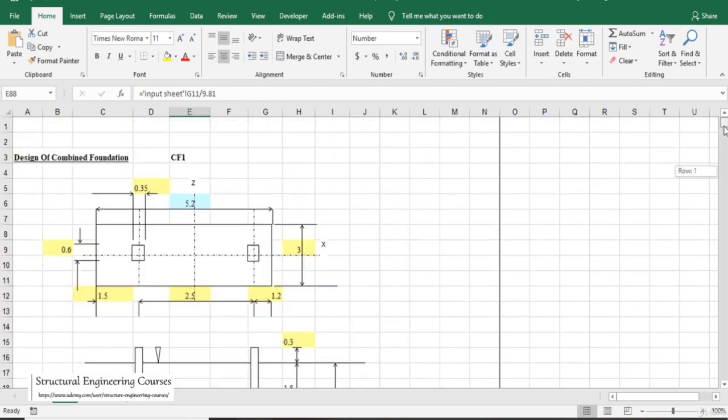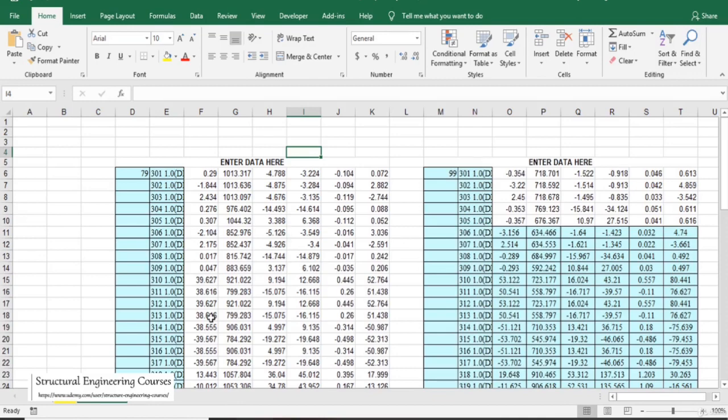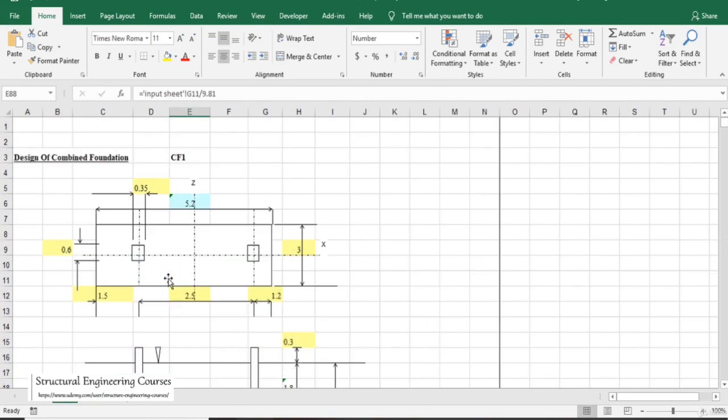So why are we comparing both the cells? It is a very basic thing to understand. The vertical load is acting on these two particular columns, so this whole pad should have a particular area so that it passes the bearing pressure calculations. For example, let us say the column load coming here is approximately 100 ton, and the column load coming here is 120 ton. So the total is 120 plus 100, that is 220 ton.